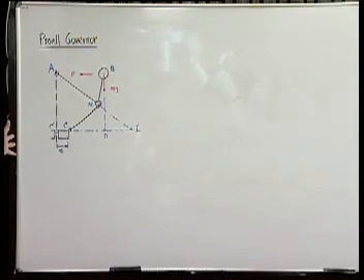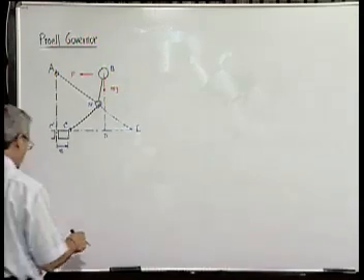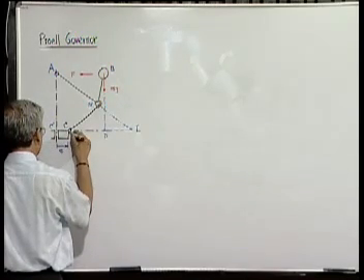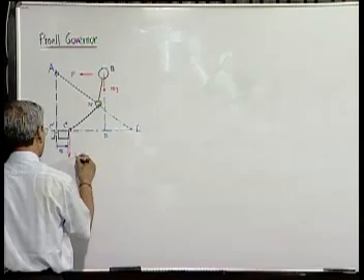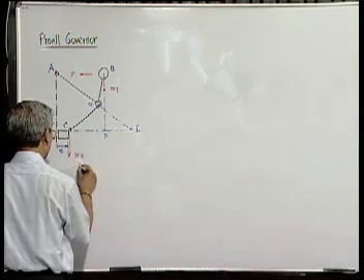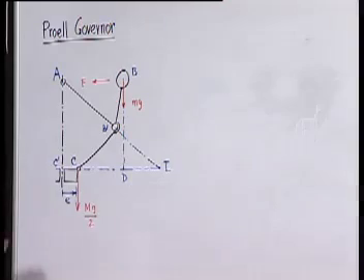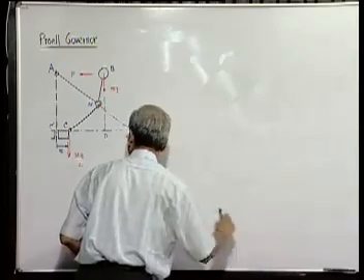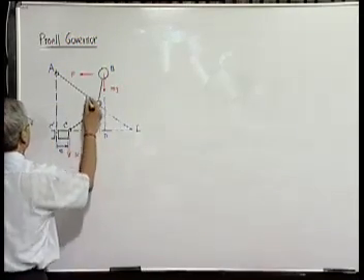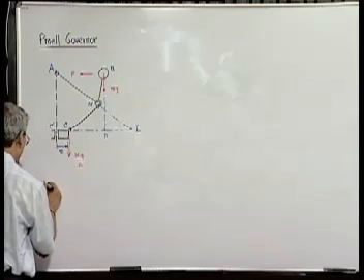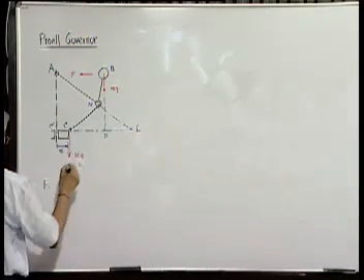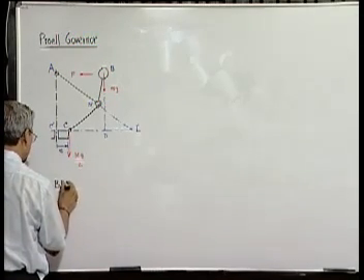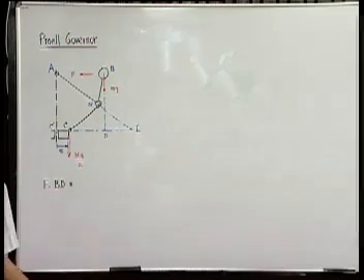So this is a particular configured situation at a particular speed, and here of course the force is acting on this, and that is half the sleeve load, because the other half will act on this side. So here, in this particular case, if we take the moment of this representative force F about I, it is F into BD. BD is the perpendicular distance from the point I.